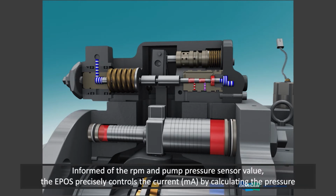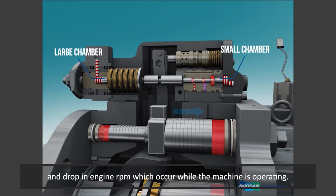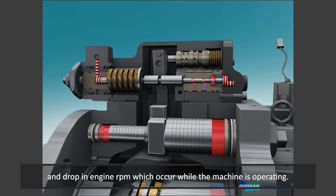Informed of the RPM and pump pressure sensor value, the EPOS precisely controls the current, milliamp, by calculating the pressure and drop in engine RPM which occur while the machine is operating.